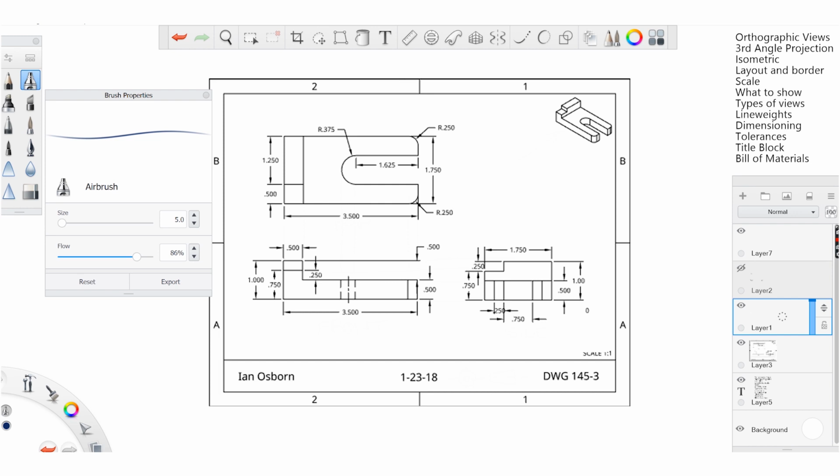It is basically changing an isometric view, which you see here, into its 2D features or 2D projections, which are what you see here. In this, we just have a top, front and side view, and you see that via third angle projection. Third angle projection is represented by this little symbol here, which basically tells you that you're going to see the front of the object, and then projected to the side will be the right hand side, aka the front and then the right hand side. Therefore you'll then have a top view.